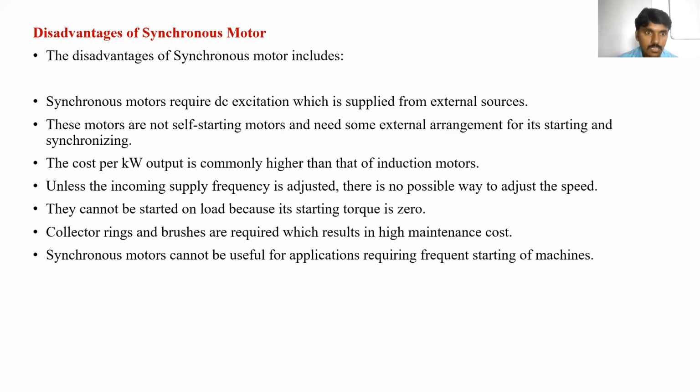These motors are not self-starting motors and need some external arrangement for starting and synchronizing. As we know, the three-phase induction motor is self-starting, but the single-phase induction motor is not self-starting, so we use capacitors to start it. In the same way, the synchronous motor also does not have sufficient starting torque. Due to this, we have to arrange some external arrangement for starting.